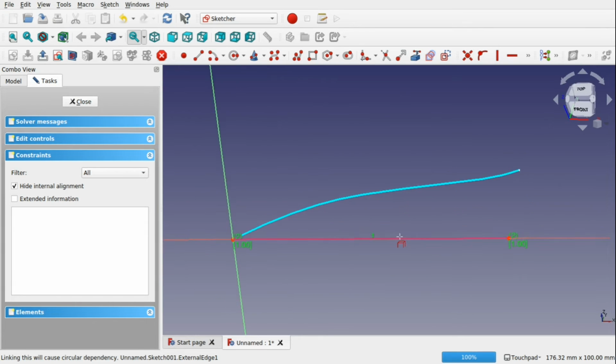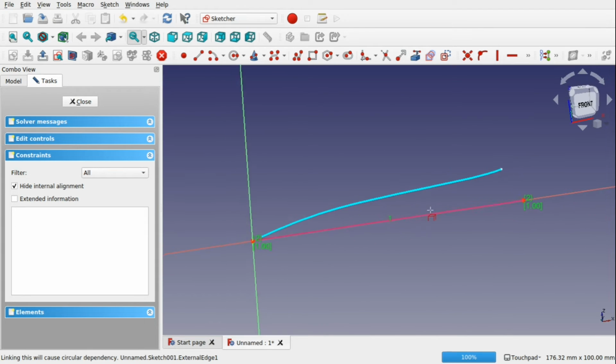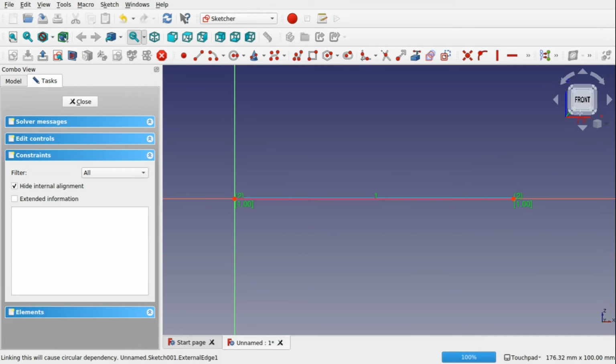This is important that we do this, because we don't want our sketch for the front profile or the side profile to go beyond this point here. So if I place a line here, so it's nice and straight, we've got our vertical constraint coming in there.